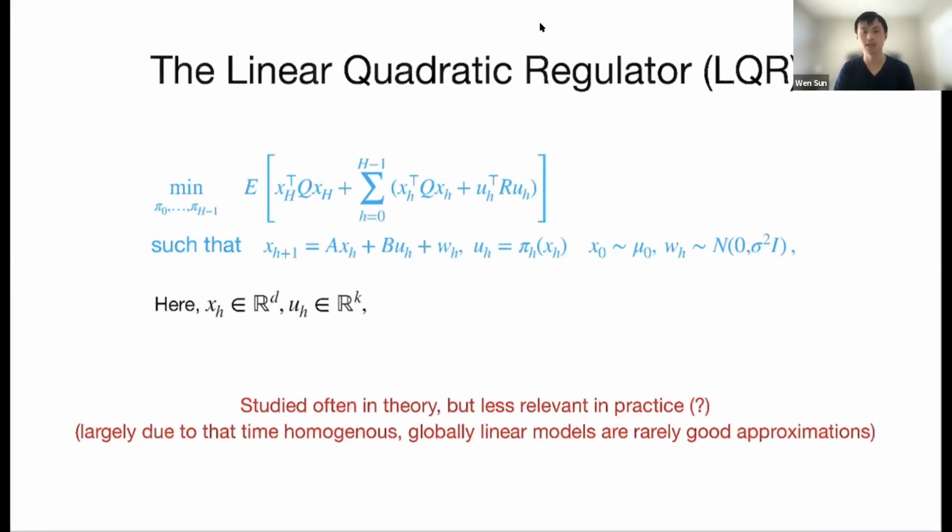But as we will see next week, this linear quadratic regulator often serves as an approximation oracle that we can use to compute locally optimal solutions for nonlinear control problems. Right? So one thing that we will do in homework is basically take a nonlinear dynamical system. We're just going to linearize it along some waypoints, right? So we locally approximate nonlinear models using linear models, right? We do a first order Taylor expansion, for instance. And then we just use LQR to compute the optimal solution. And then we repeat the process. Right, we will talk about this next week.